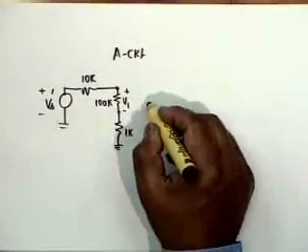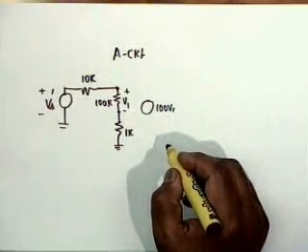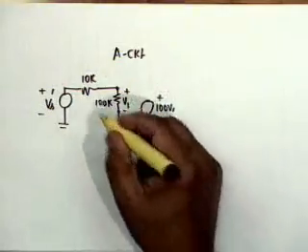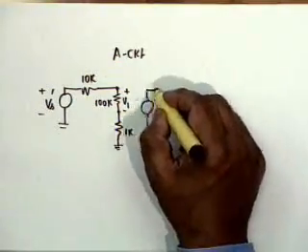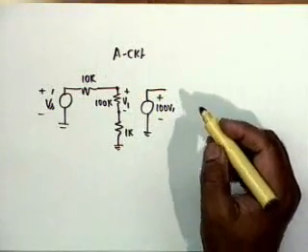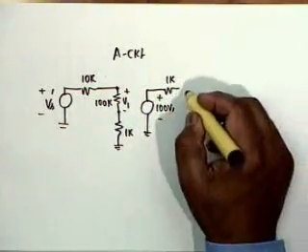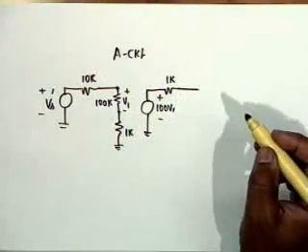Okay, fine. So we go to the model. The differential gain is given as 100, so 100 V1. Too many hundreds and tens, don't confuse. Then it has an output resistance. The differential amplifier has an output resistance of 1K, so 1K goes here. Then comes the model.